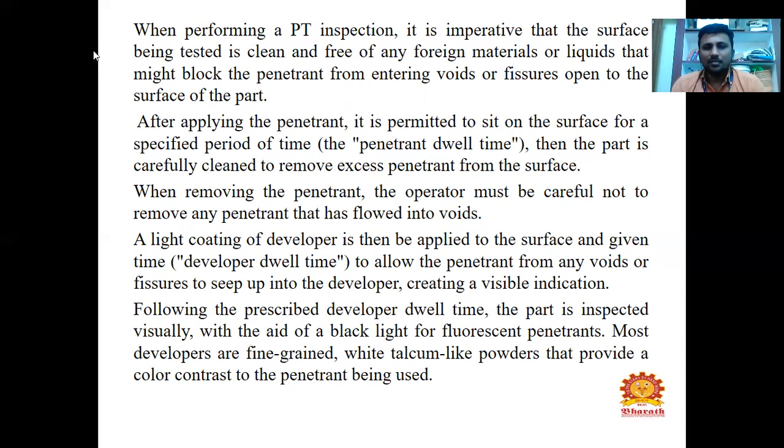Following the prescribed developer dwell time, the part is inspected visually, with the aid of black light for fluorescent penetrants. Most developers are fine-grained, white, talcum-like powder that provides a color contrast to the penetrant being used.